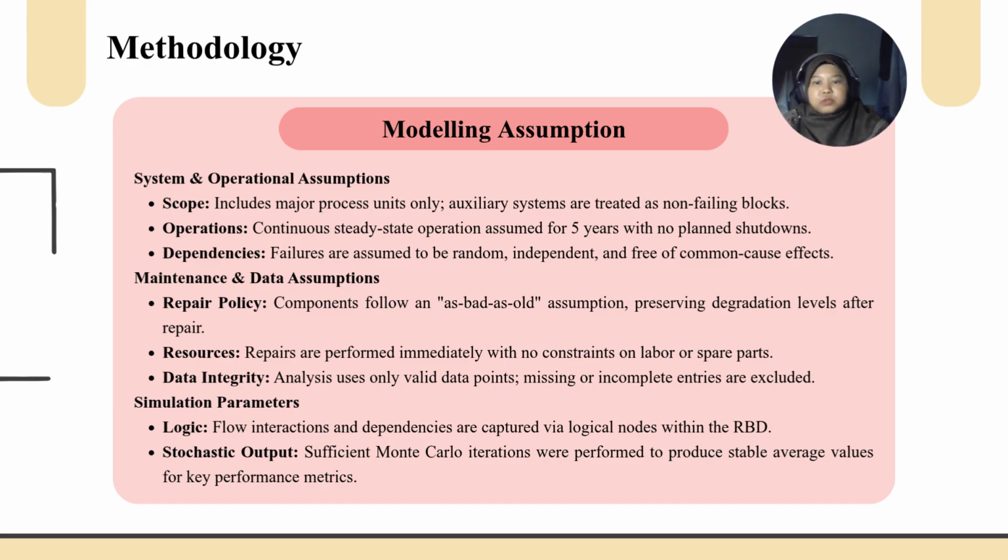We also assume a continuous steady-state operation over the 5-year study period, meaning no planned turnarounds were included in this specific model. Crucially, for our maintenance logic, we applied the as-bad-as-old repair assumption. This is a conservative and realistic approach where a repaired component does not return to as-new condition, but instead retains its accumulated degradation. We also assume unconstrained resources, meaning repairs begin immediately without waiting for spare parts or labor. Lastly, all failures were treated as independent events, allowing us to isolate the specific factors that are truly driving plant downtime. Next, we move to the next slide.